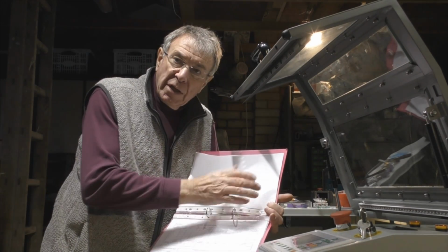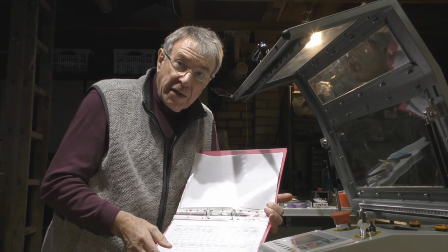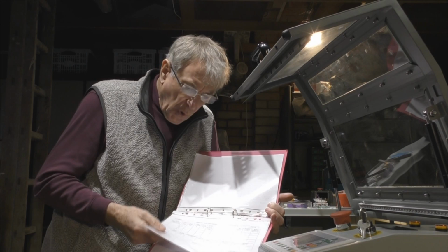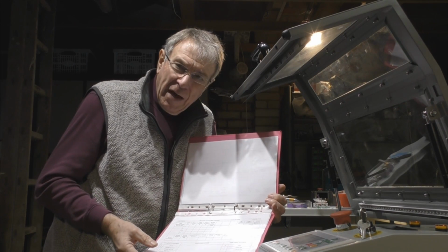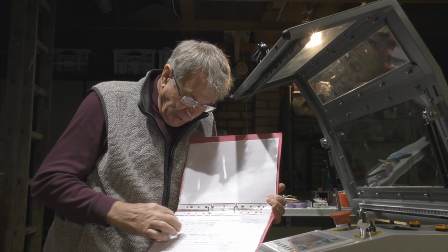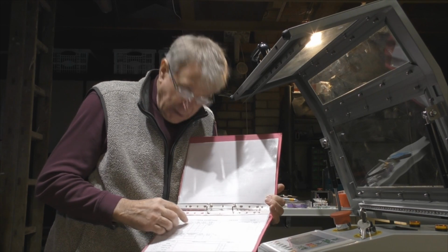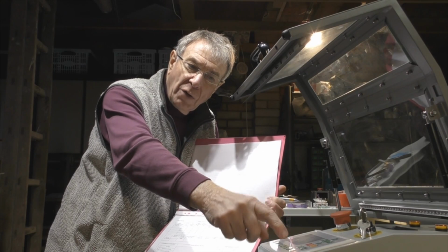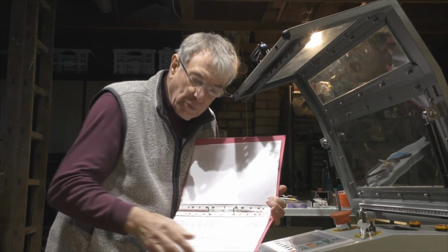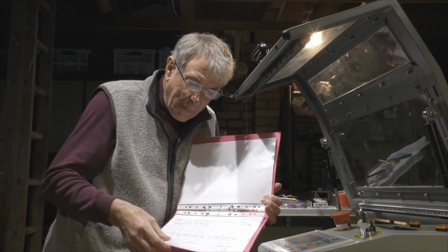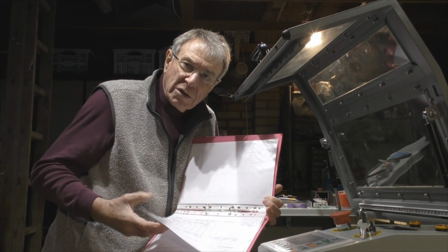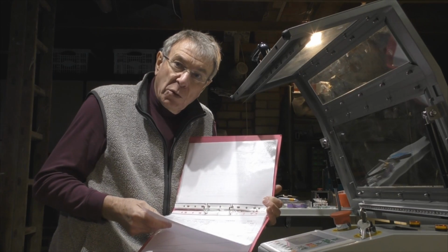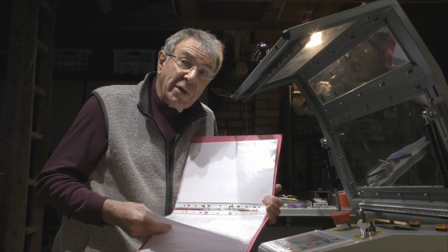Okay, so you've spent ages creating all this lovely data. You decide you need another machine. Maybe it's going to be an 80 watt machine as opposed to a 60 watt machine. How do these parameters work for you then? You need to be very careful because you'll be putting all this information here in something called percentage power, which is what you see on the display here. That's what this machine works in, percentage powers. It doesn't work in watts. So all the parameters that you've got in here could actually be quite meaningless if you move to another machine.